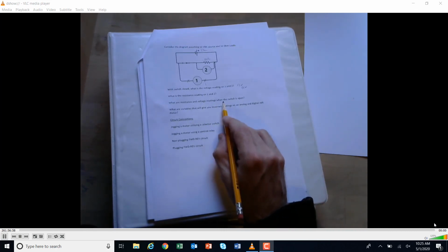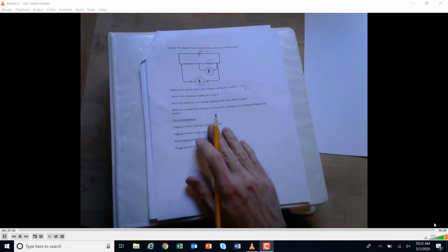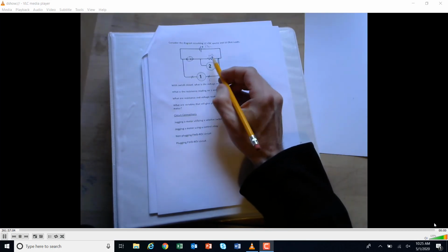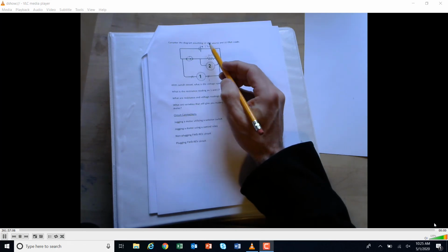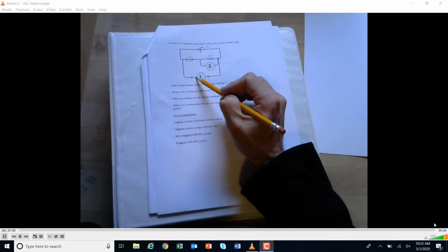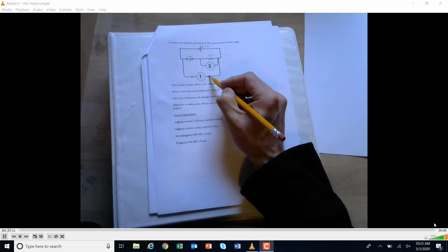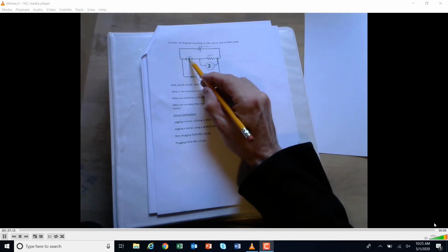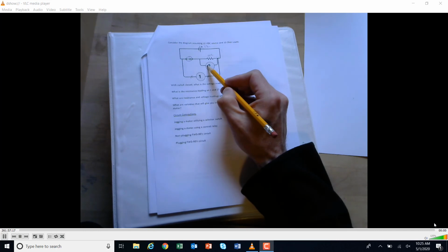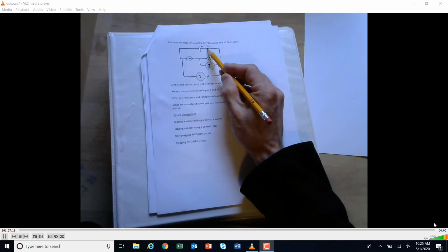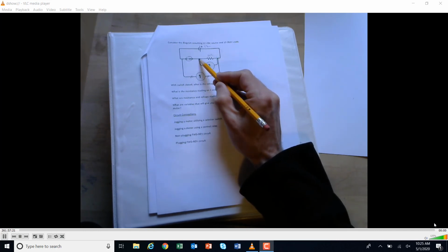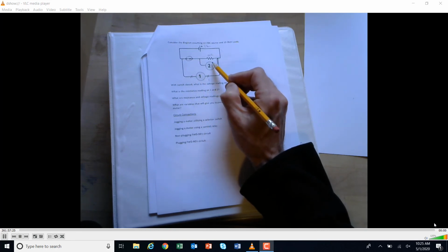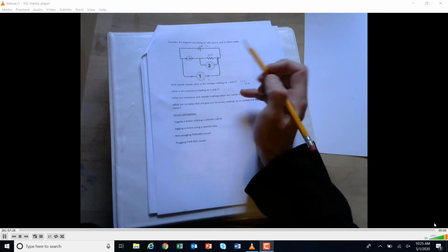When it's open, when the switch is open, that's different. Because when this opens right here, okay, well, on number 1 right here, I still have plus, and I still have a path to minus, so I can still get 12 volts. When this is open, for number 2, I have a path to this side, but I don't have a path here because that's open. So I would say 0 volts I would get there.